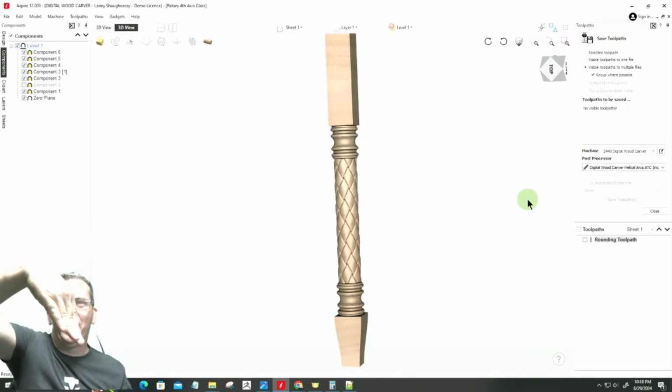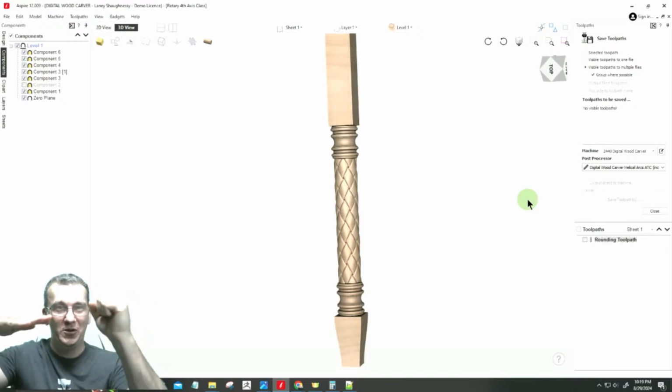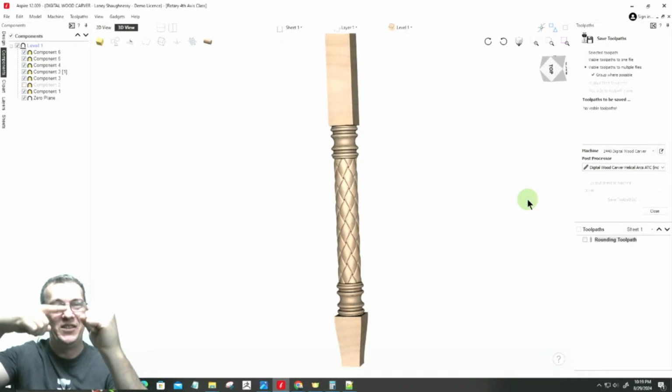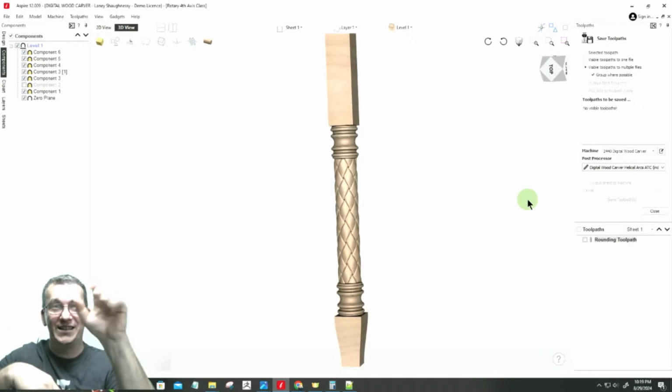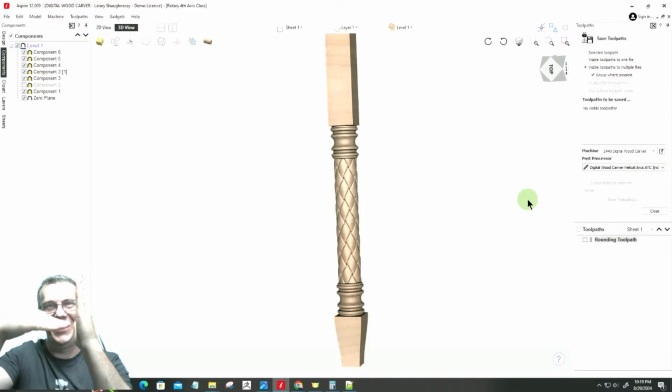Well, when the router pivots 90 degrees on the 2440, the Y-axis movement is now the Z-axis. The tip of that bit is moving towards the stock over here, so it's going in and out. So that Y-axis movement is Z. The A-axis, which is the rotary axis, is Y, the rotation. X is still the same. Z is still the same. And A is when the bit is centered up and down on the stock, the Z becomes the A, up and down.